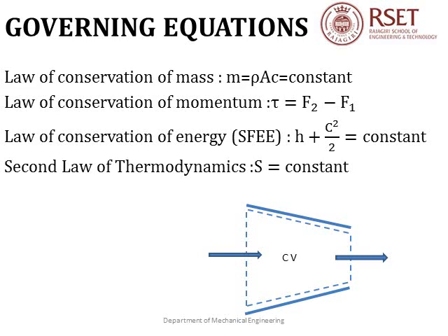So, the law of conservation of mass reduces to this simple form for an isentropic flow. Next, we have the law of conservation of momentum, also known as the momentum equation. Here, we have the sum of external forces acting on the control volume equal to the difference of inertia force of fluid in and out of the control volume.